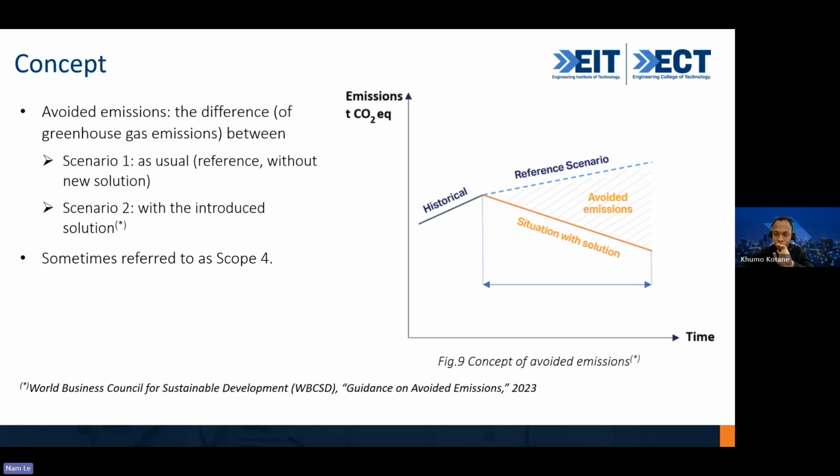And with the new solution, we have something new, because typically people cannot use a very high slag percentage. They can only use 20, or maybe try a little more, 30 or 40%, but 60 or 70% is something like impossible because of barriers like workability and strength, right? And this is when we have the new solution, when we introduce new admixtures, and we can use a higher percentage. This is new.